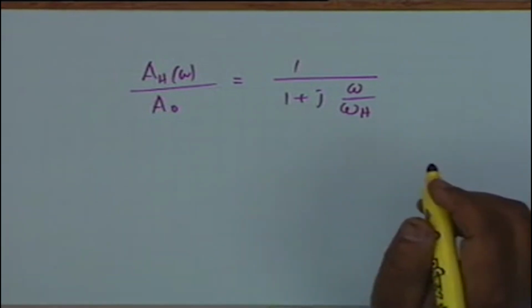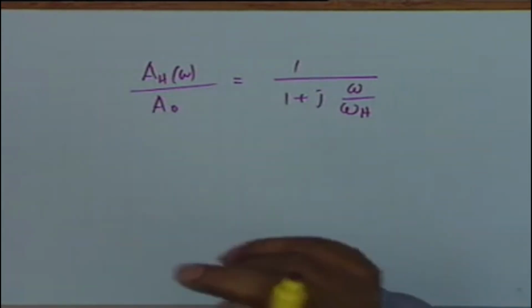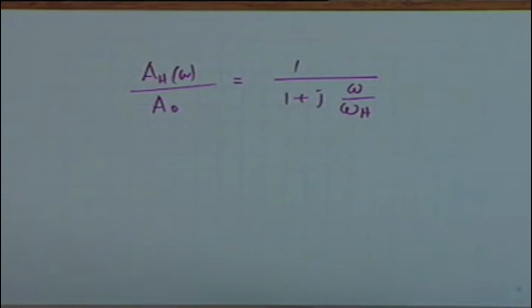Is that okay? There are no other capacitors determining the omega h. Why not? We had started with 2 capacitors. How come we are left with only 1? Because we ignored CC1 and CC2 and C; they have no business to show their faces at high frequency.